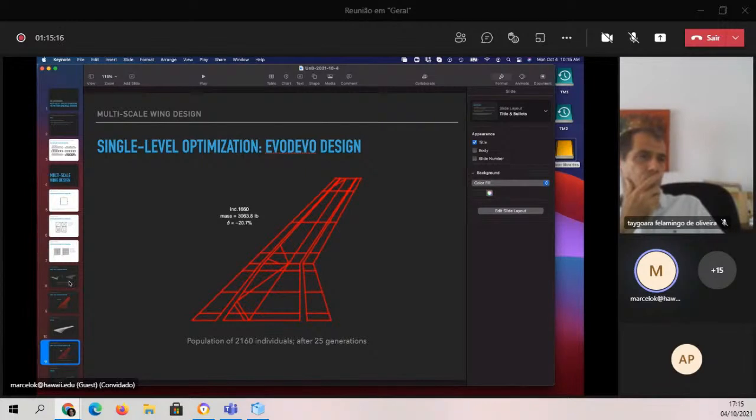So to improve the efficiency, we first performed it without flutter. We get a solution without flutter, and then we start a full solution, including flutter, that starts from the solution we obtained without flutter. So we did that in two steps to address the issue you're asking about, to make it more efficient and more stable.